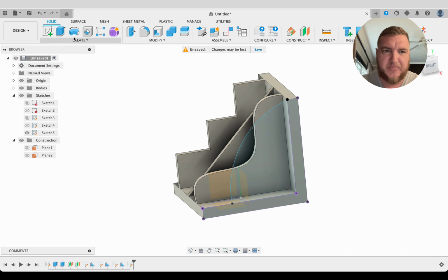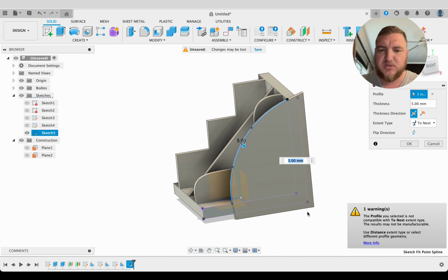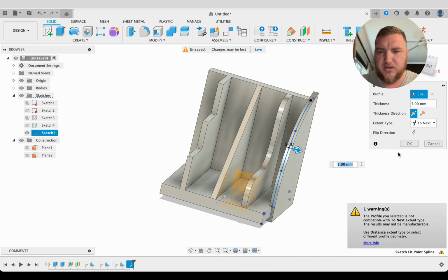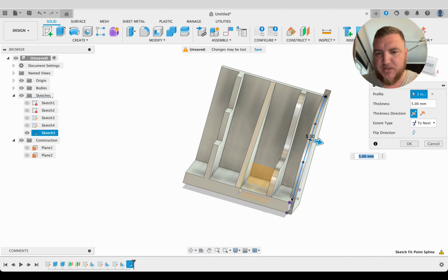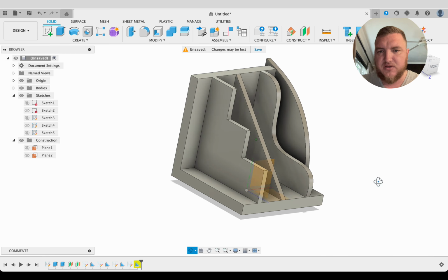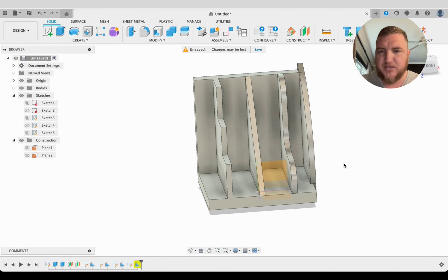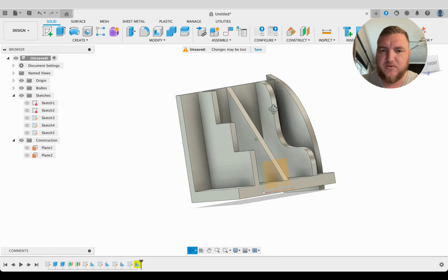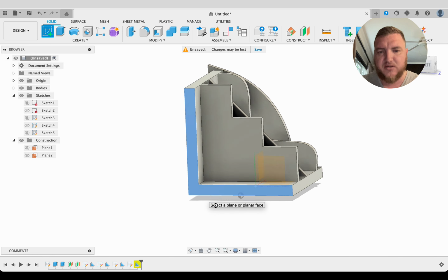Finish sketch. Again, we're going to create. Select our rib tool, and there it's going over the edge by 2.5 mils, but you can see we don't have to have it going exactly to the edges over there. We could have the rib starting anywhere on this shape. In fact, let's just do another one here.